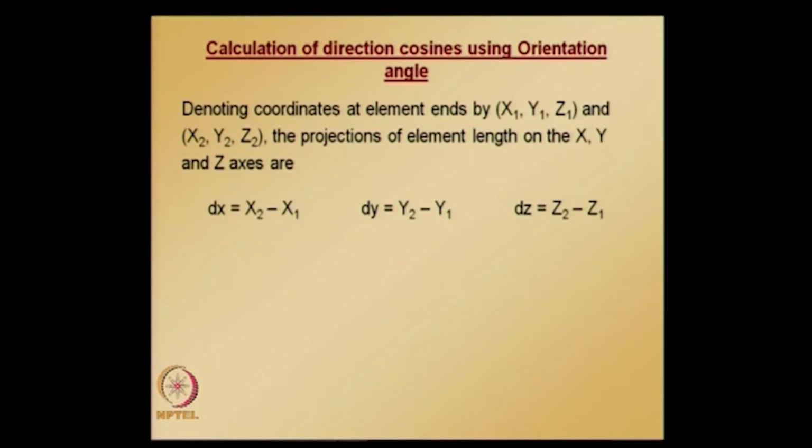The projections of the element length on the capital X, capital Y, capital Z axes, you are already familiar with this. dx is equal to the difference between the x coordinates of the 2 ends. Similarly dy, dz. Once we know dx, dy, dz, we can calculate the length of this space frame element.